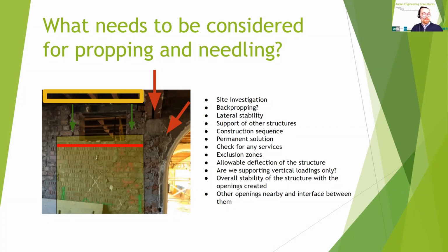Check for any services. Are there any, are they live, and can they be redirected or do they need support? Exclusion zones: are there any local exclusion zones required? Or can there be some exclusion zones in place during the prop installation, which would mitigate some of the risk associated with propping loads if we remove some of the loads from the structure?